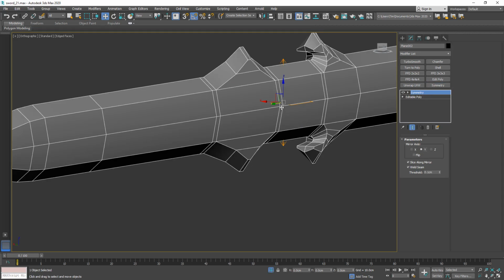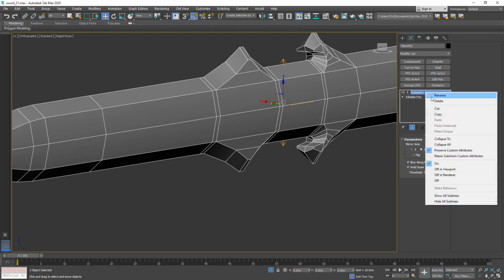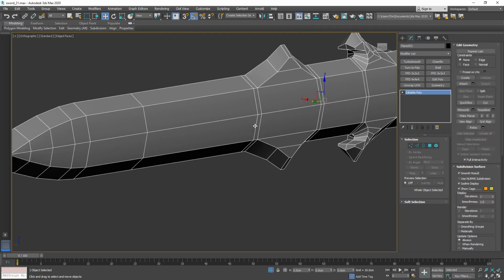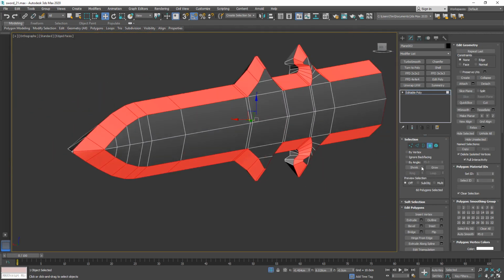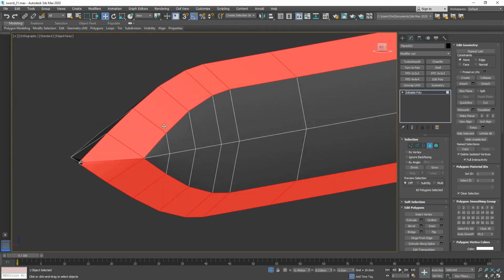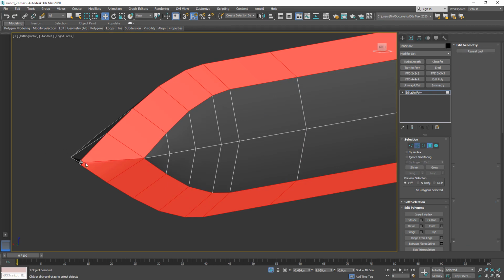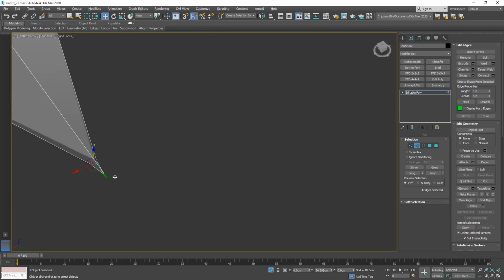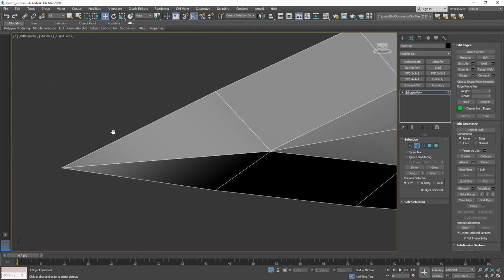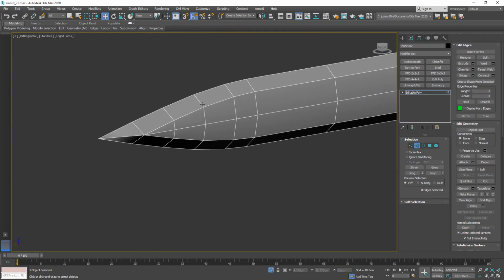Now I'm gonna have our symmetry modifier here on the y-axis so that we have this curvature or this angle also to the bottom. So now let's go back here to that selection. I'm gonna auto smooth it once more, and I'm gonna zoom in here, double click that edge, and press Ctrl Backspace to get rid of this little edge loop that we don't need there.